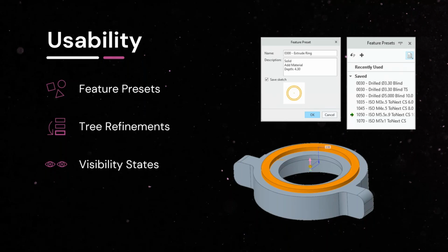to your designs. So feature presets are predetermined, pre-planned features for things like holes, extrudes, revolves, rounds, chamfers, and curve from equations. PTC are looking to expand this, but if we take a hole, for example, maybe you have a particular hole, it's always the same diameter, it's a drilled hole, it's a through all, and it's got a countersink on it.